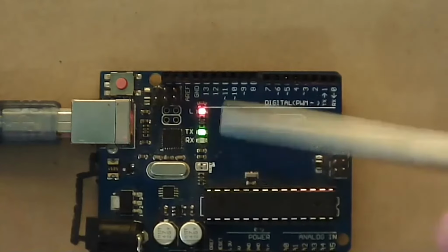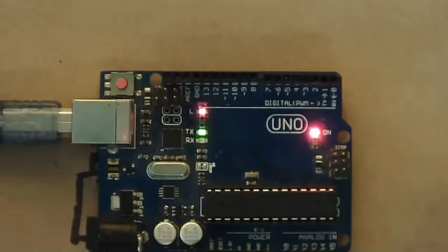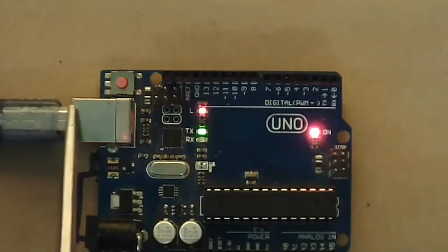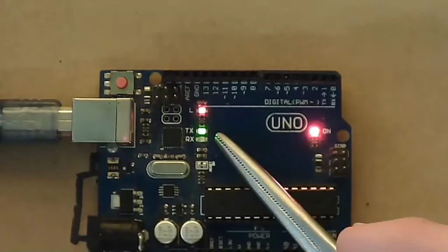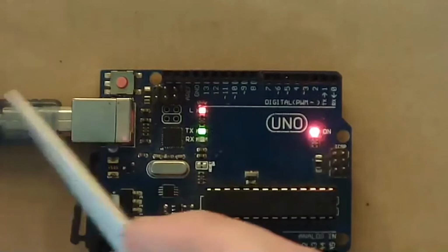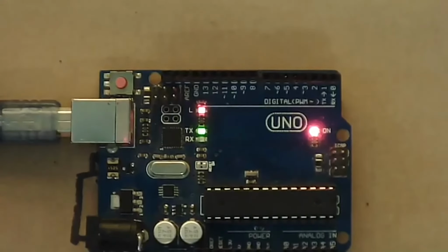And if I had just loaded up the blank Arduino sketch, we wouldn't see this light on. When I do the actual act of loading the sketch, I'll just press load the sketch, and we'll see both of those lights blink. Because during the process of loading the sketch via our USB connection, data is coming across. That's why our RX was flashing, and then the TX will flash basically like confirmation that the sketch is successfully loaded.